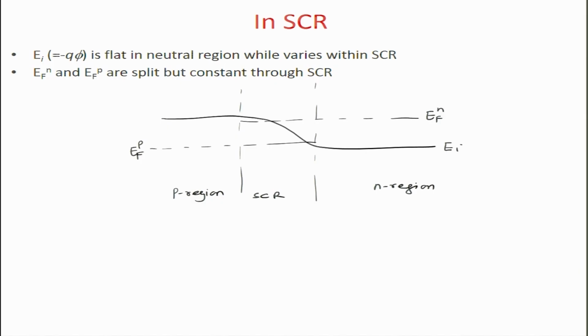when you expose the semiconductor to a lot of light, you create conditions which are not neutral conditions. As a result, you flood the semiconductor with excess carriers on both sides. So, the N side becomes extremely rich in electrons because you have suddenly excited a lot of electrons from the valence to conduction band. Similarly, the P side becomes flooded with carriers. So, as a result, the Fermi levels move away.